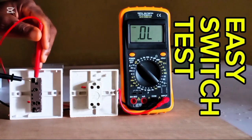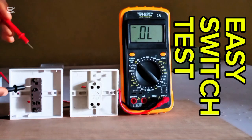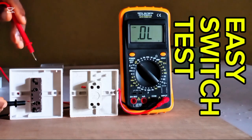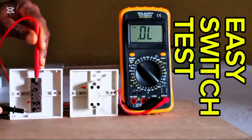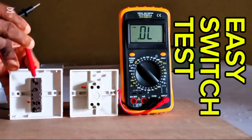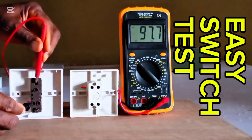The two-way switch has three terminals: common, line 1, line 2. Inside this rectangular block, there are connecting bars linking common to line 1, common to line 2, so that when we test and flip the switch, they will read. So this is what we are going to do now to know whether the switch is in order or not. So we flip here and test common to line 1.